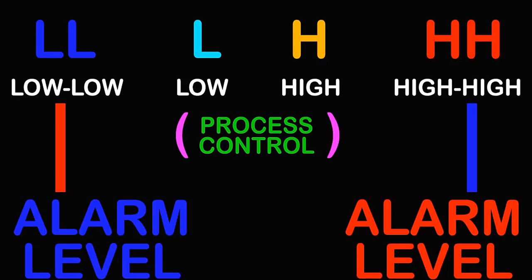And we exceed our 80 degree set point, and maybe once we get up to 90 degrees, we have a high limit set in our program that notifies the operator there's a problem, something's wrong, and again, possibly it interrupts the process, or possibly it has a way of cutting the heat somewhere upstream, maybe at a power supply that isn't dependent upon that relay for control.